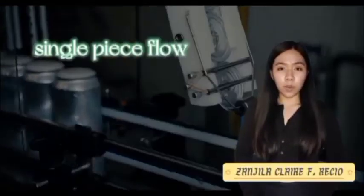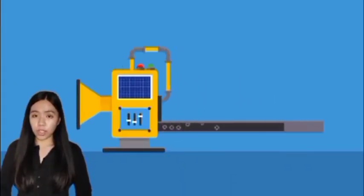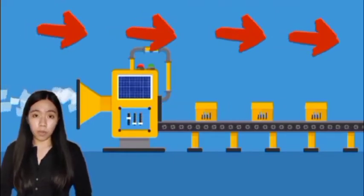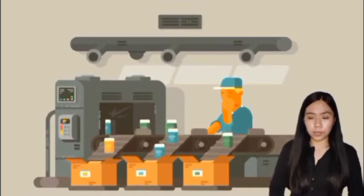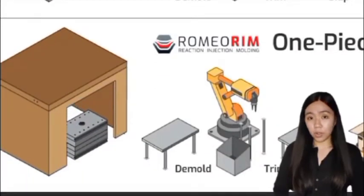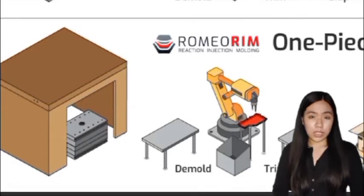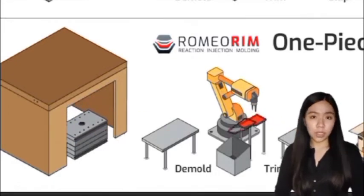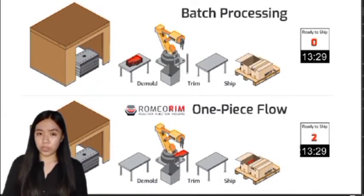The single-piece flow, or continuous flow manufacturing, is a technique used to manufacture components in a cellular environment. The goal of single-piece flow is to make one part at a time and correctly all the time without lengthy queues. Imagine an area, called a cell, where everything needed to process the part is within easy reach, and no part is allowed to get to the next operation until the previous operation has been completed. Take a look at this illustration.